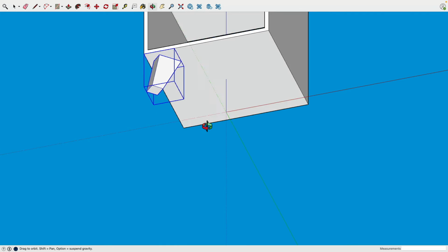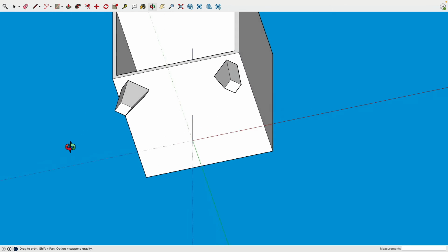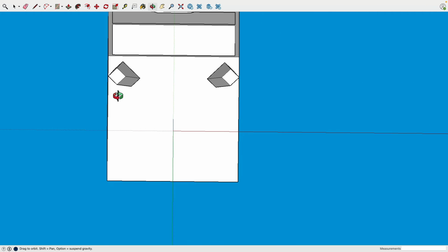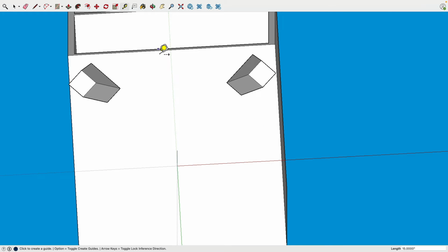we have to bring this over now as a copy. This is a rectangular base, so this makes it a little bit easy. We can go to rotate to the center. I just tapped the Alt or Option key, click at the center, click on the X axis and Y there. Bring one copy over. That's actually very useful because now in this view we can plug down another guideline.